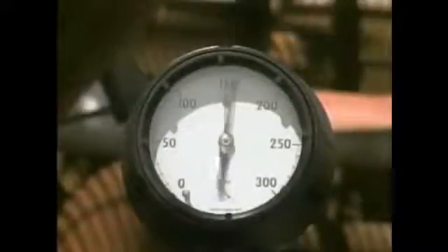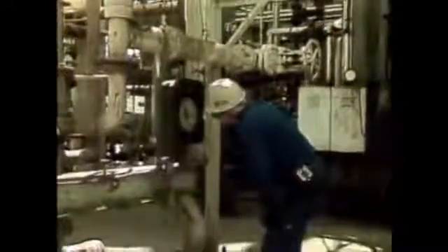When you hear a rattling noise that sounds like marbles rattling around inside the pump, it's usually a sign of cavitation. Other signs of cavitation include fluctuations in discharge pressure and sometimes an overheated pump casing. Cavitation can also cause a decrease in flow. The extent to which flow decreases depends on how bad the cavitation is. Cavitation is usually violent, and if it's not corrected, the pump can be damaged.